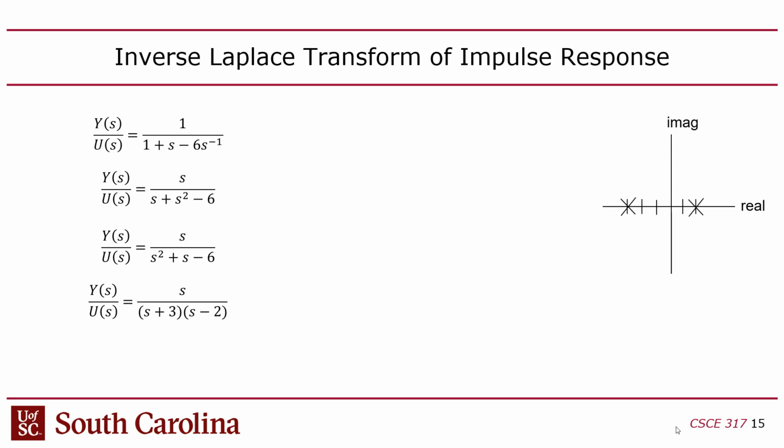So generally, there's this thing called a pole and zero chart. You'll often see where they take the imaginary part of the number as the y-axis, and the x-axis is the real part, and then for the poles you put an x, and for the zeros you put a little o. But in our case, we only care about the x's, the poles. Notice that one of these x's is on the left-hand plane, to the left of the vertical axis, and the other one's on the right-hand plane, which means it's not stable.